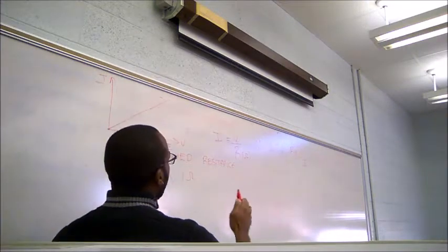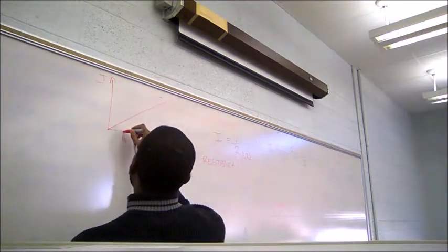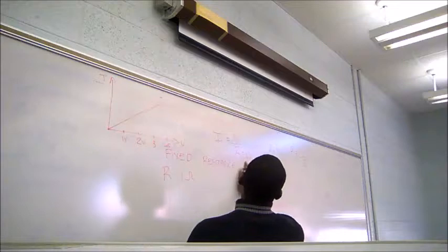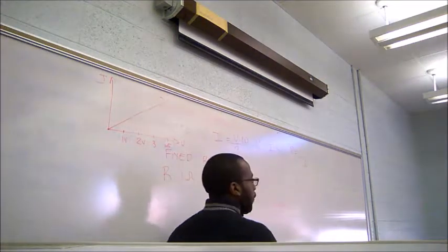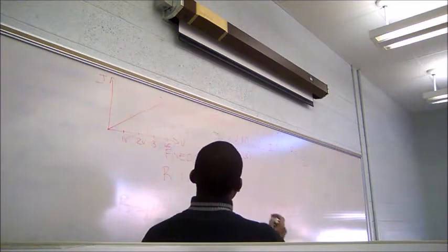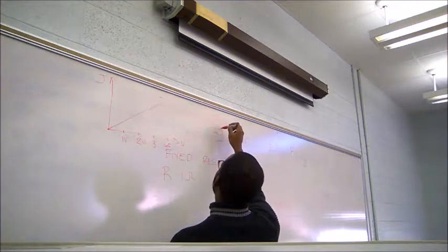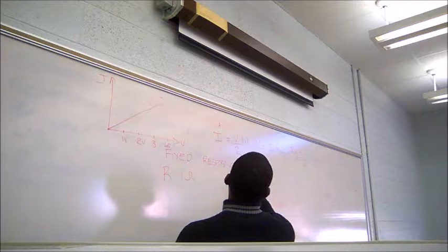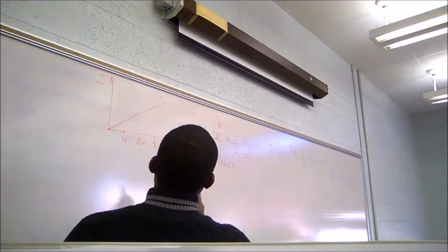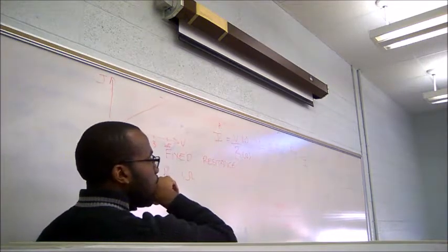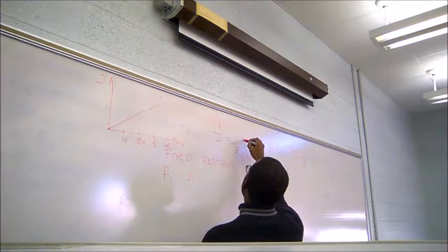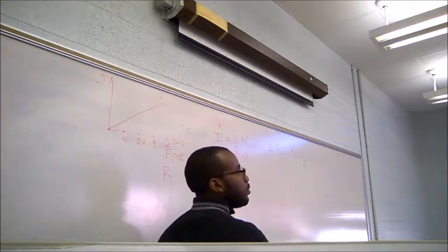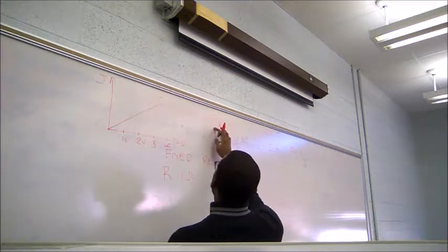Voltage pushes the current. What happens when we go to a voltage of 1 volt here? Remember we have 1 ohm here. What will our current be? 1 ampere. Remember, this is fixed, 1 ohm. What happens when we go to 2 volts? According to our equation, 2 over 1 is what? 2. So our current is going to be 2 amperes.